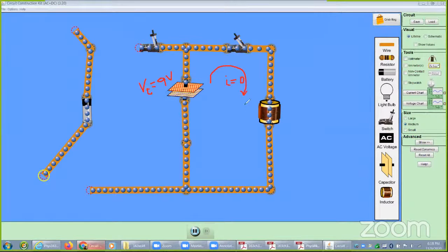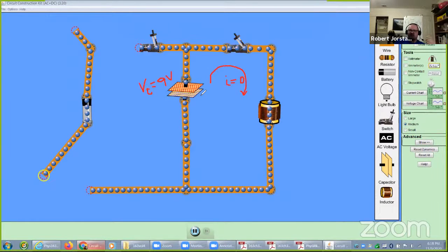Yeah. So nothing is wrong here. This does not break any laws of physics. The capacitor preserves its voltage at 9. The inductor preserves its current at 0. Gradually, however, there's a tiny amount of resistance in this wire, but let's assume it's pretty negligible. So eventually the current should start to flow, right? And eventually you're going to have a large current flowing through the inductor. Eventually.